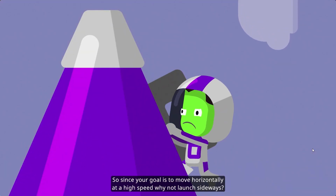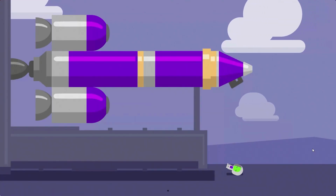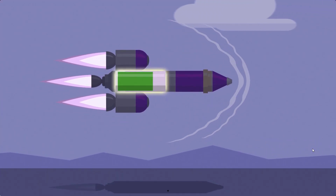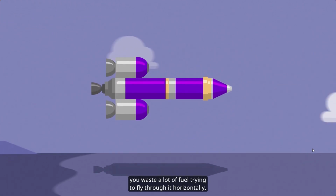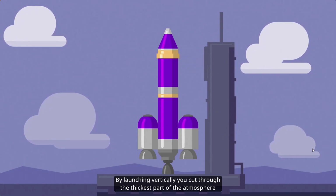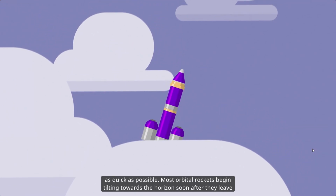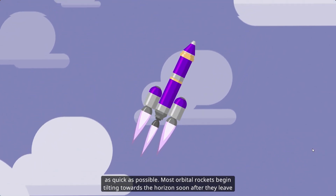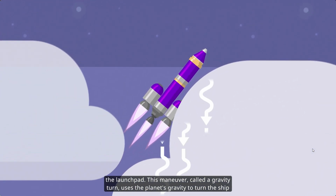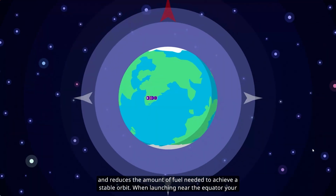So since your goal is to move horizontally at a high speed, why not launch sideways? On Kerbin, the atmosphere is like a thick soup. You waste a lot of fuel trying to fly through it horizontally. By launching vertically, you cut through the thickest part of the atmosphere as quick as possible. Most orbital rockets begin tilting toward the horizon soon after they leave the launch pad. This maneuver, called a gravity turn, uses the planet's gravity to turn the ship and reduces the amount of fuel needed to achieve a stable orbit.